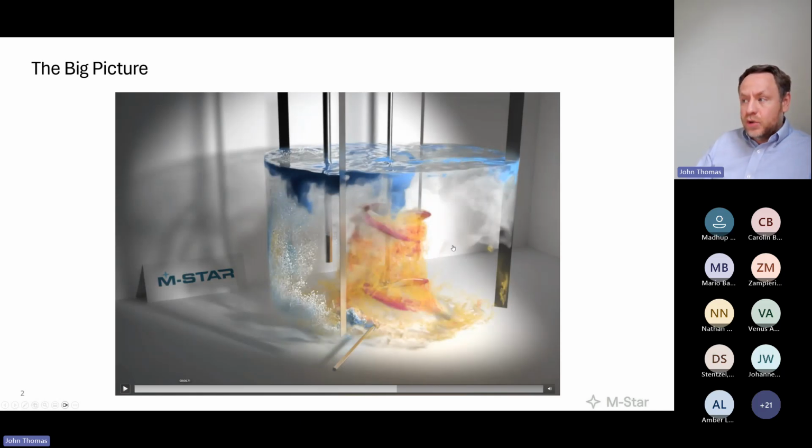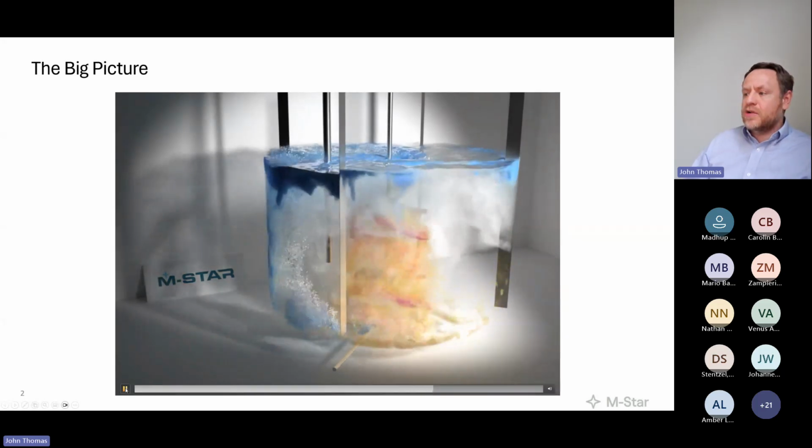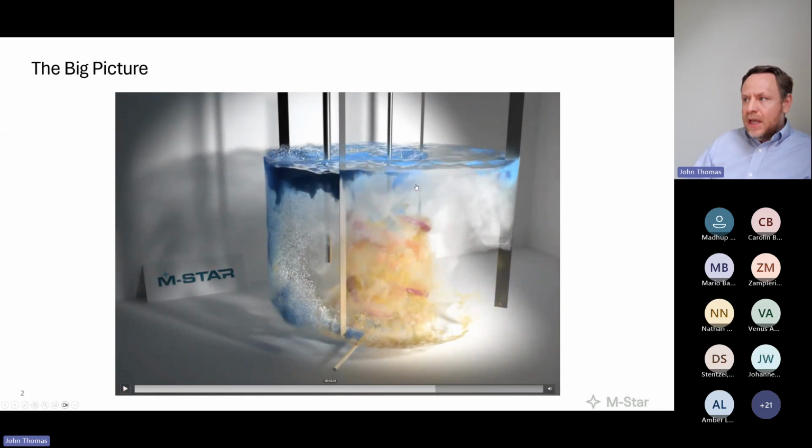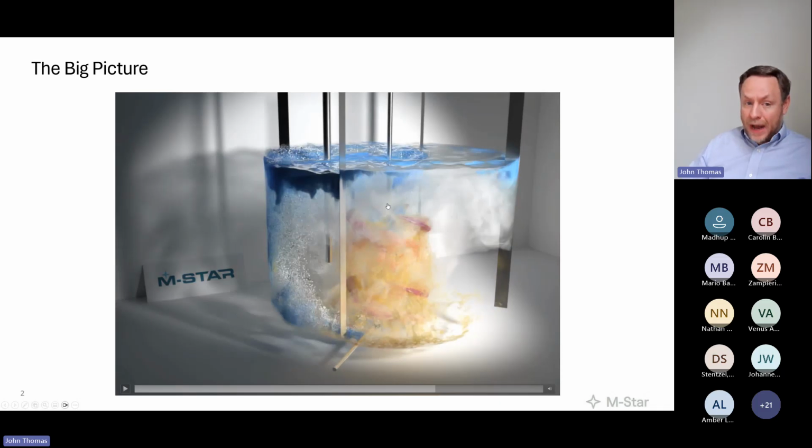And now, if an oxygen molecule arrives in this fluid, we might have a hard time discovering which path it came through. So we just have a probe stuck inside this vessel and it's measuring the time evolution of the DO concentration, trying to figure out what the effect of KLA or HLA might have been if we have both physics present, particularly if we have headspace present in tandem with sparged gases. What our probe is measuring is going to be a mixture of the net effect of those two individual transport processes. So when we're characterizing KLA or trying to measure KLA, as it were, we've got to make sure that we're contextualizing, understanding, and scoping any free surface transport that might exist inside the system.